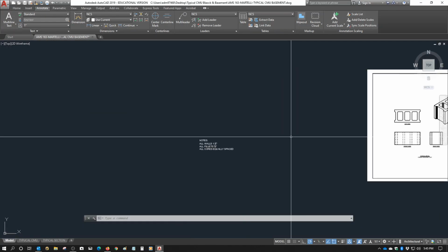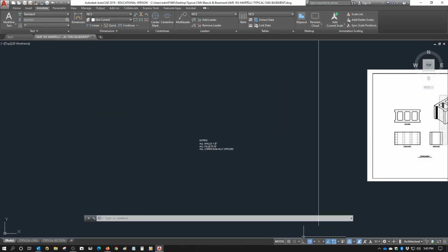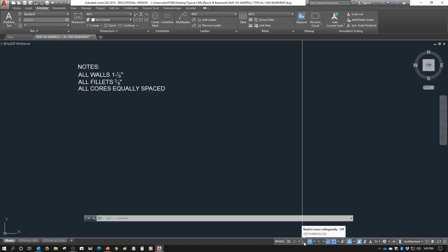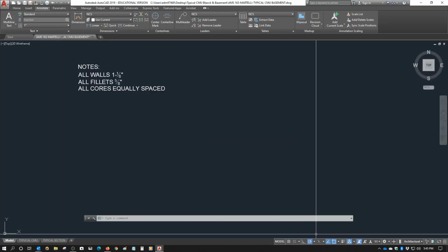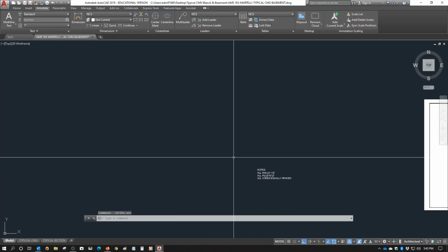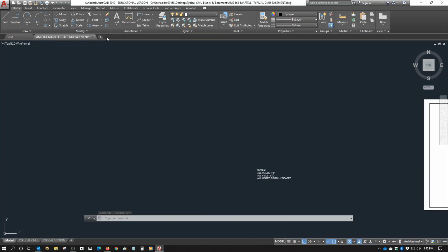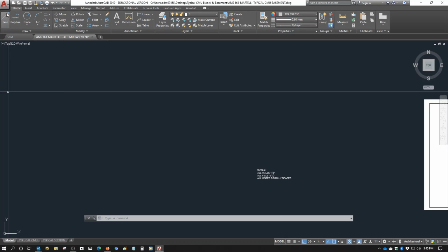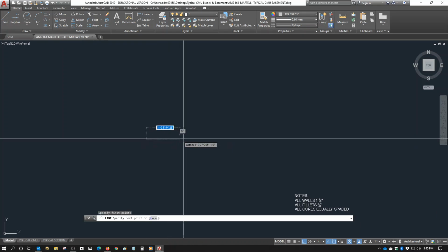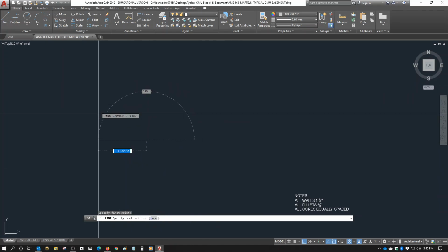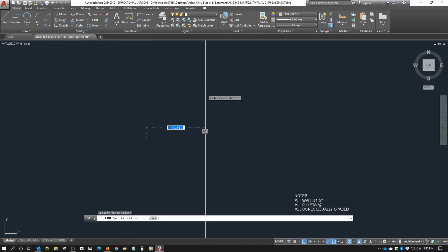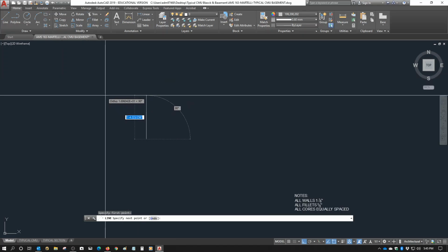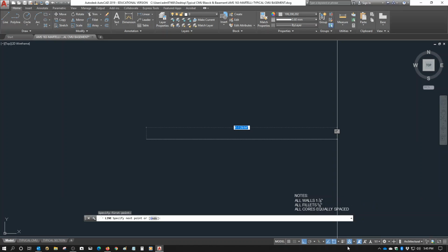So I'm going to start off now. Something else: polar and ortho. I'm going to go into ortho mode, which looks like the perpendicular symbol, and I'm going to pick line command somewhere up here. Go to home, and the line I want to draw, maybe choose a different color, like a cement looking color maybe. And then with my line thickness, I want to go 0.6 millimeter. Pick line command, and somewhere up here, pick a line. Now notice one thing. I changed my line weight. First of all, ortho will only let you draw 90 degrees at a time, right? But I chose line weight, but line weight's not showing up.